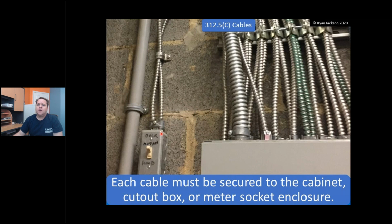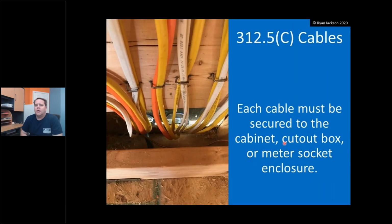So in this photograph, here on the left, we have a device box. That's not covered by Article 312. That's covered by Article 314. This cabinet here is covered by Article 312. Now, this rule says each cable must be secured to the cabinet, cutout box, or meter socket enclosure, and you can see each of those cables is in fact secured. Easy enough. Here we have another example of the same requirement. We've got a cabinet for a panelboard, multiple cables going into it, and they're all connected to that cabinet.